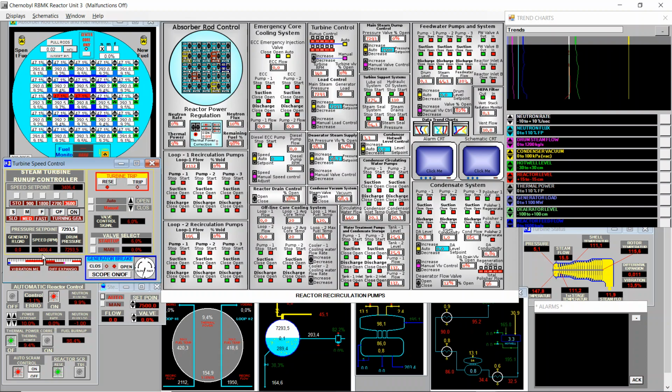We're at 200 RPMs of the nominal, and I will just start the oscilloscope now. Now it's rotating like crazy because we are far from nominal. So once we reach nominal, we need to stabilize as close as possible to 3600, then increase the power set point to a higher value like 9 or 10,000, so we are sure that we have an increasing pressure rate, so we don't have a negative or reverse polarity in the generator.